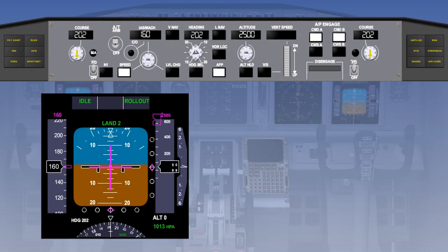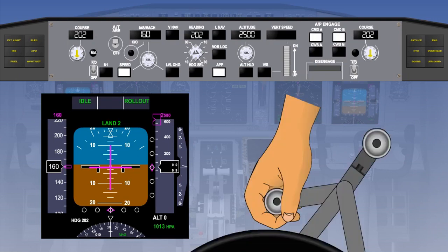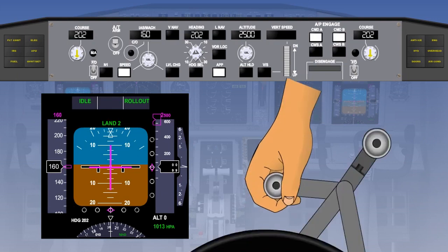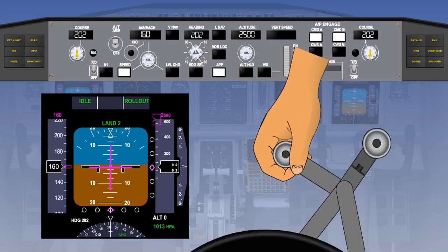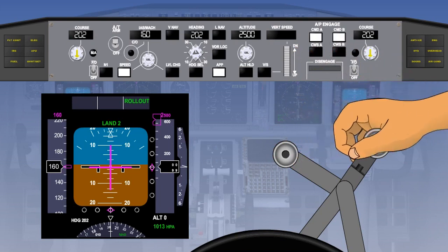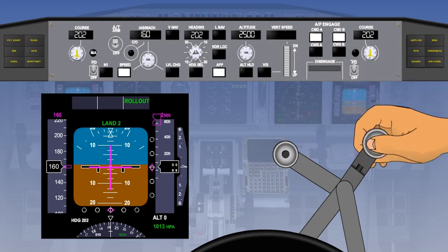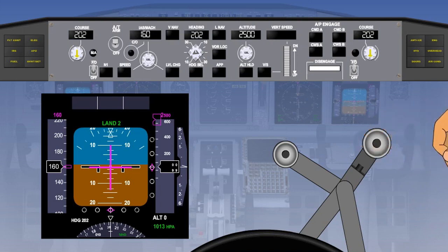The aeroplane then transitions into the touchdown and rollout mode, which causes the nose to be lowered and the speed brakes and auto brake to be applied if selected. When reverse thrust is applied by the crew, the autothrottles disengage. If the aircraft does not have rollout control or guidance as part of the Autoland system, the autopilot will be disengaged at this point, and the rollout controlled manually.